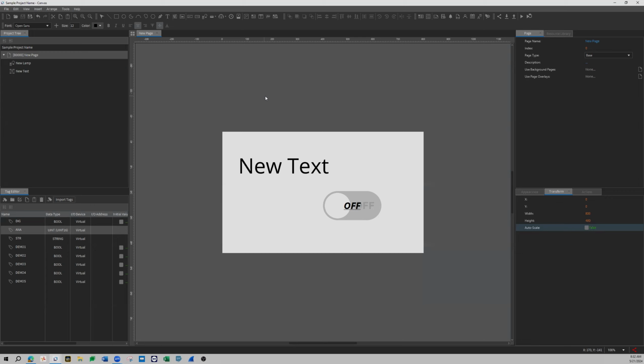The aspect ratios might be a little different because 4-inch and 7-inch are widescreen. So you're creating a project for a widescreen HMI, but I think 10, 15, and 12 would be appropriate to swap between, and 4 and 7 should be appropriate to swap between. Just be careful about what you're downloading to.